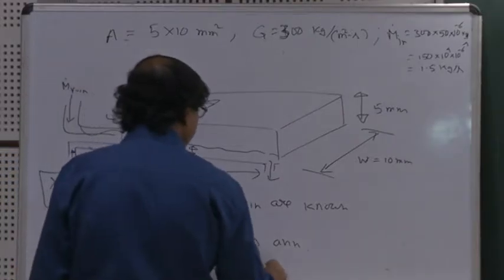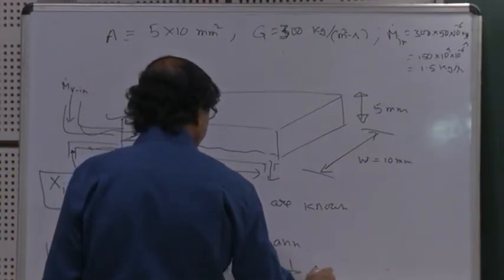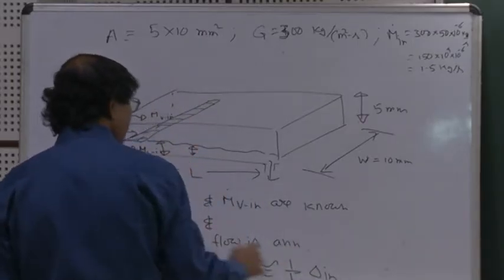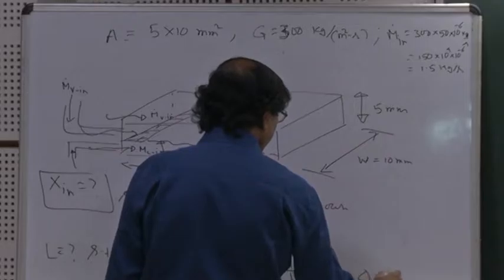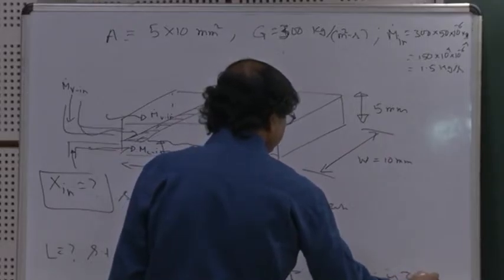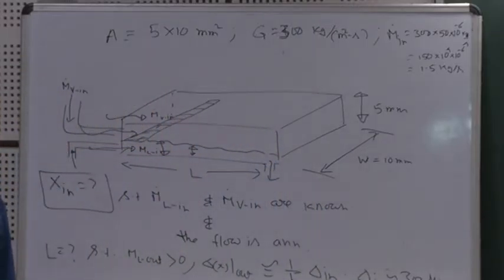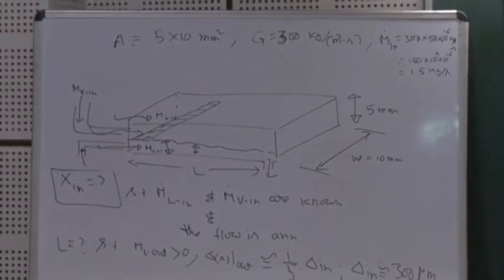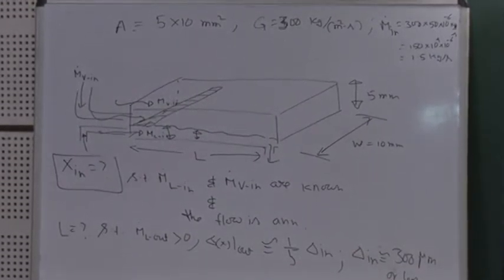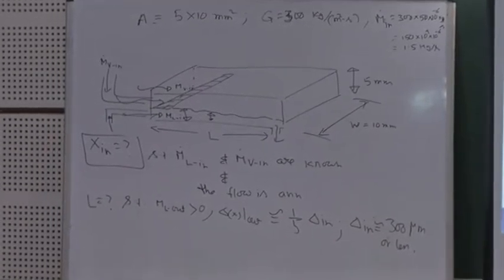Delta X out is, say, 1/10 or 1/5 of delta in. I want delta in to be of the order of 300 microns or less. So all these put a lot of constraints. And if you just say, no, I want to do a micrometer scale boiling and condensing flow, so I will start with 100 micron and 50 micron diameter tubes, what's going to happen is that you may fulfill your desire that you did an experiment, but you will have huge pressure drops and a lot of problems in realizing any goal.